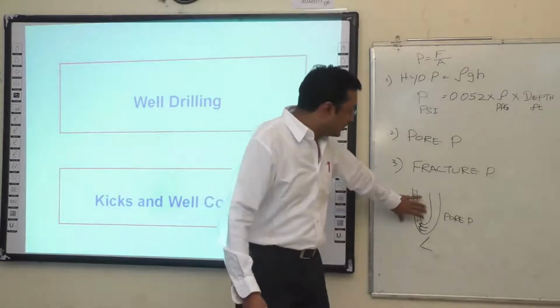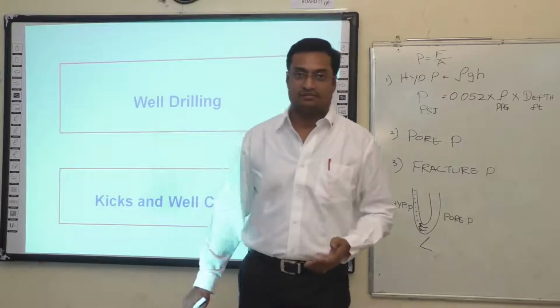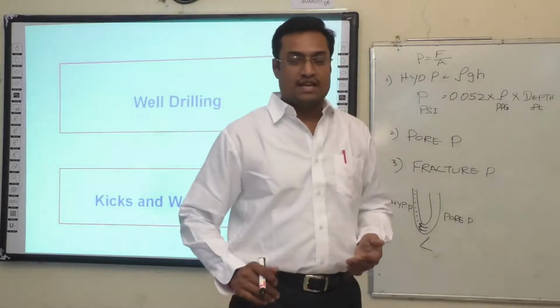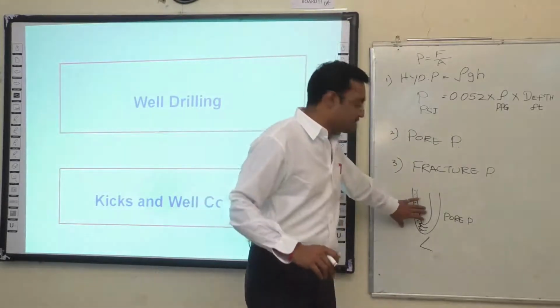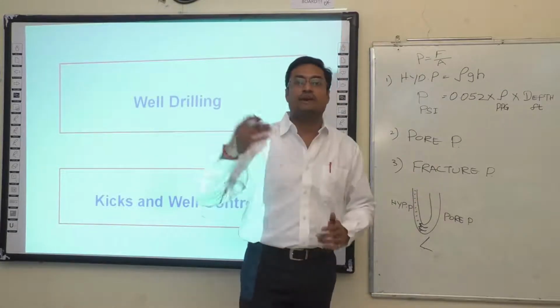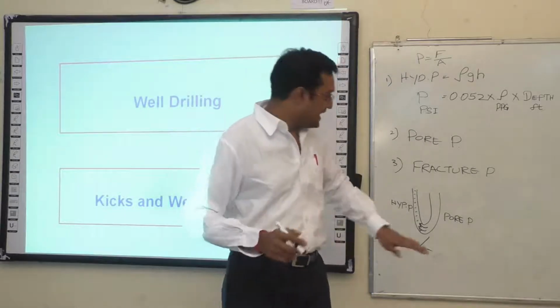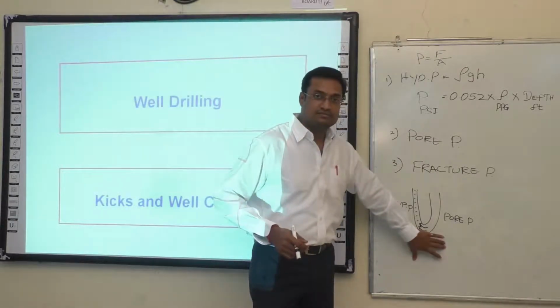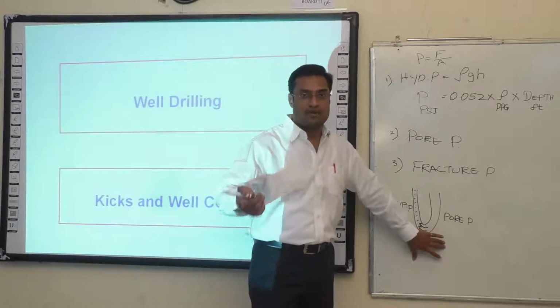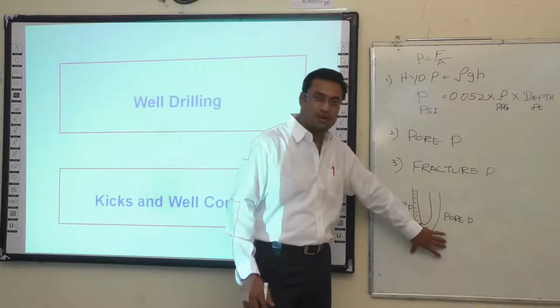If we lose this control, it is very difficult to proceed further with drilling. If you don't understand the situation and we proceed with drilling, we aggravate the problem. So when we get into underbalance condition, whether you are aware of it or unaware of it, we have to make sure that we have the control.